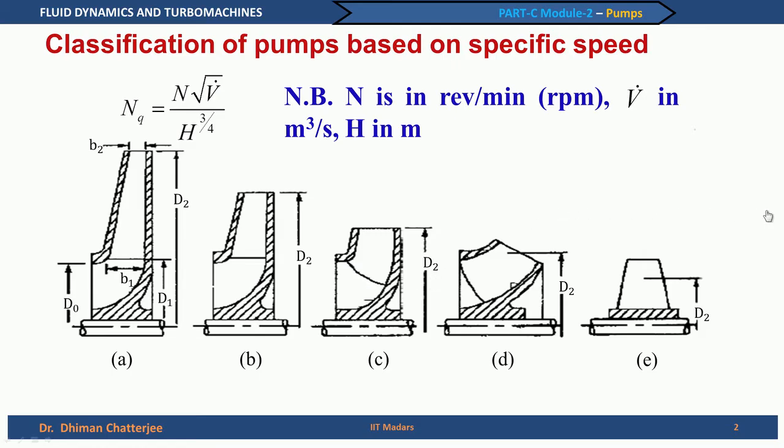This is because as you reduce the diameter d2, the blade length in this simple radial flow case will also reduce. If the blade length reduces, the guidance to the flow will be improper. Hence, in order to extend the guidance and increase the length of the blade a little more, the impeller has been drawn almost to the eye of the impeller, and the edge is made curved, so that the blade length can be somewhat compensated, though the d2 by d1 has reduced.